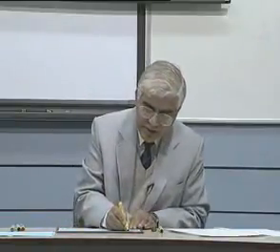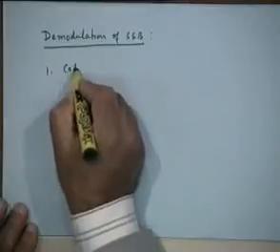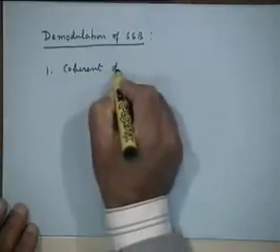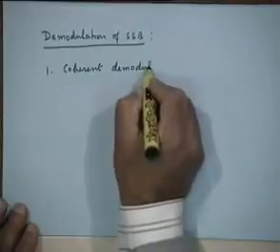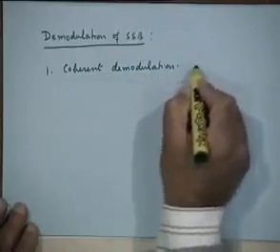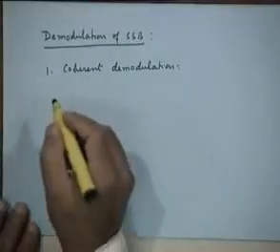The demodulator that I have discussed so far at the beginning of today's class and also mentioned earlier, what kind of a demodulator is that? What do we call it? A synchronous or coherent demodulator, right, which would require us to have a local carrier in phase synchronism and frequency synchronism with the carrier of the incoming signal. So one demodulation process is the coherent demodulation that we already discussed.